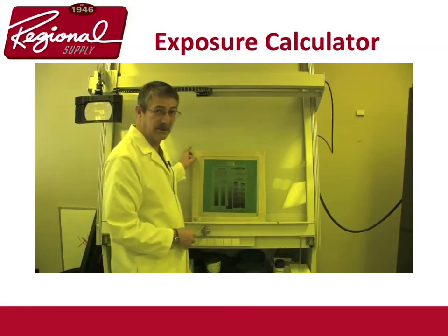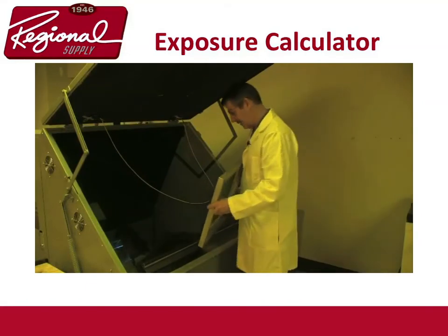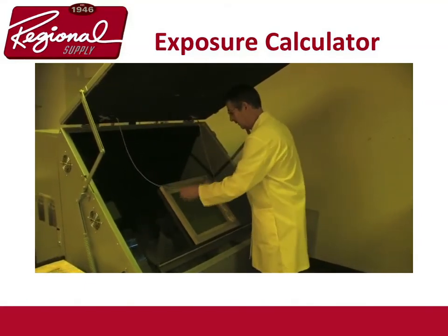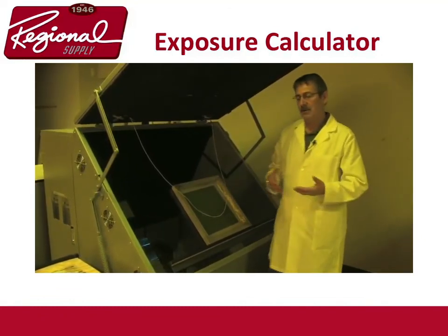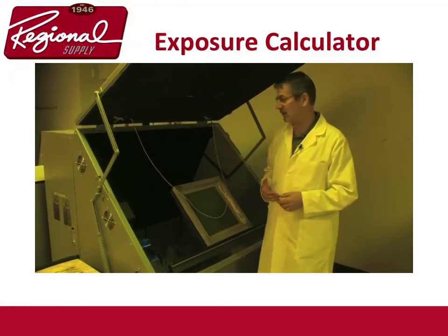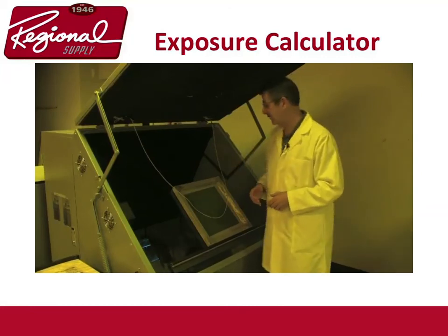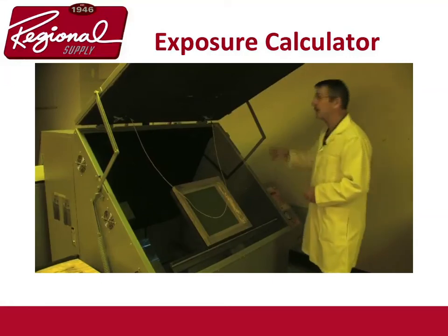Let's go to the exposure unit. All right, here we go. I'm going to put it in my exposure unit. Get it all set. Punch in a time. Now remember, we were just guessing on time. Let's just pick a minute. Remember I said you double whatever your guess is. So I say it's going to be a 1 minute exposure. Let's make it 2. That's going to be 2 minutes. And I'll draw a vacuum.